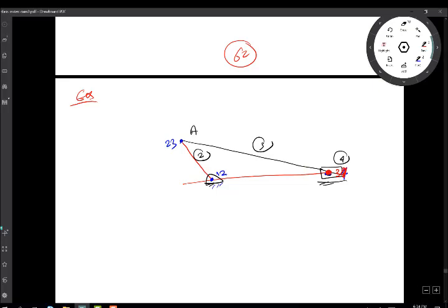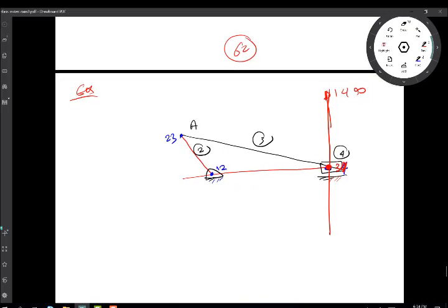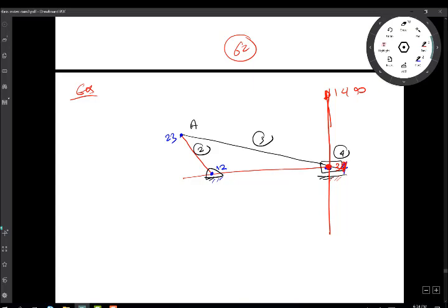Okay, so how about 1, 4? Right, 4 in fact slides on 1. Remember the pole for the sliding link? It fell, last time we discussed it, was actually perpendicular to the direction of sliding, at infinity. So point 1, 4 in this direction is actually going at infinity, right? This is 1, 4. So this specific line will then be a locus for which point?